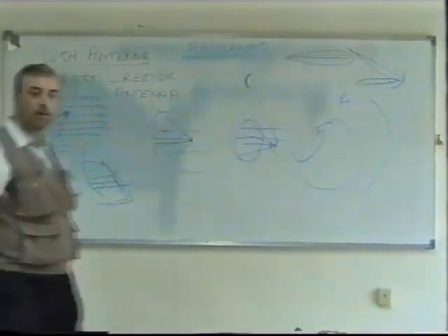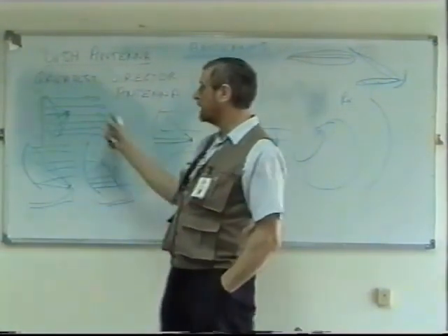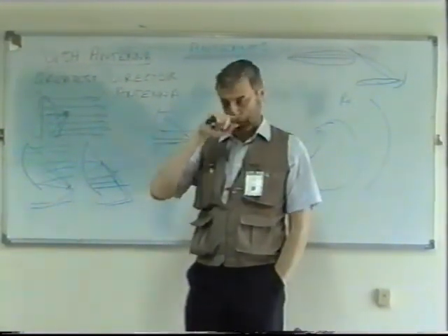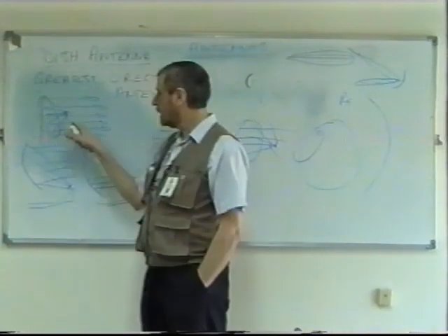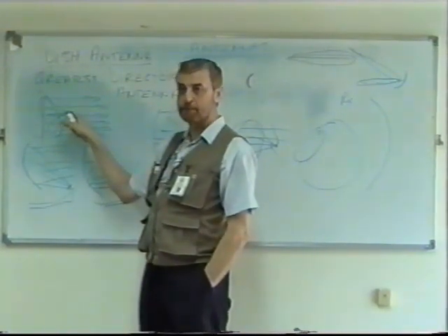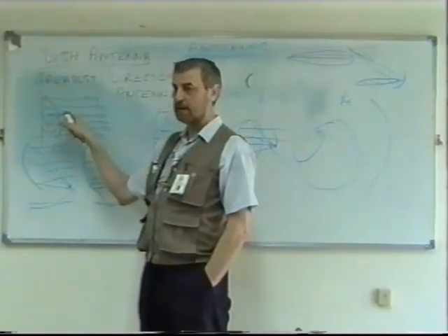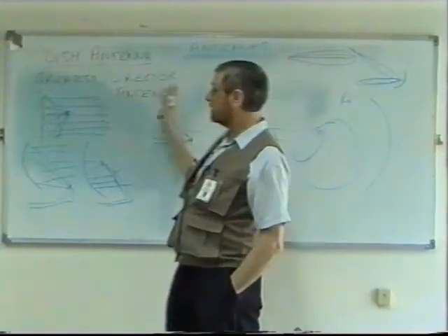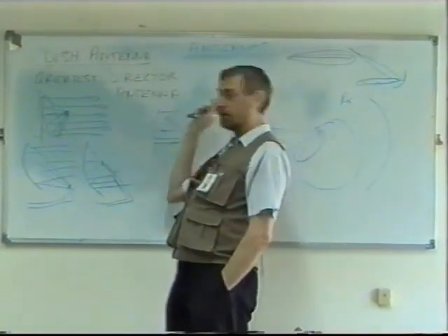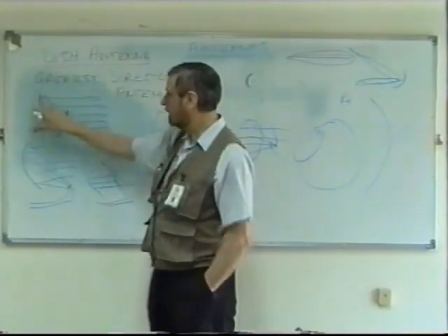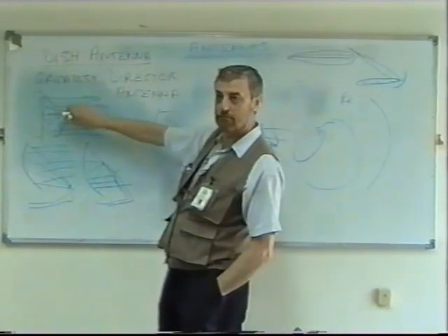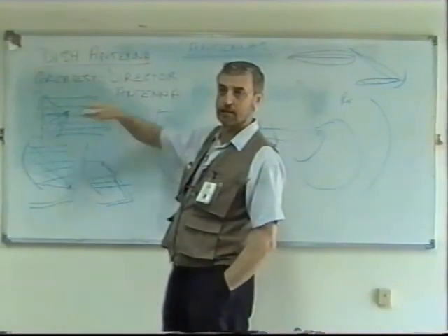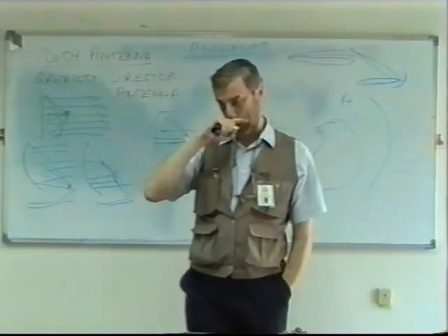What I want you to think about here is using it just for one reason, either as a transmitter or as a receiver, not both. They can actually be used for both. If it's used as a receiver, it receives the radiation from the other side, goes to the reflector, and that concentrates the beam onto the actual antenna, which is here.